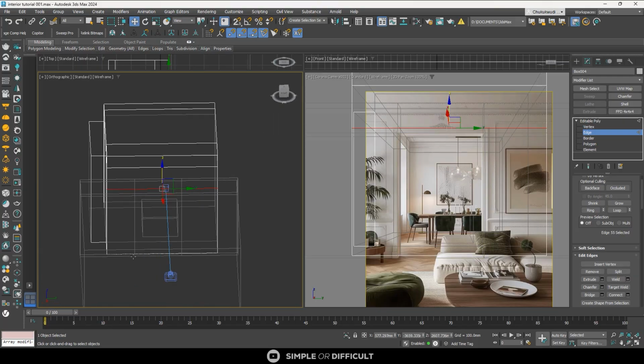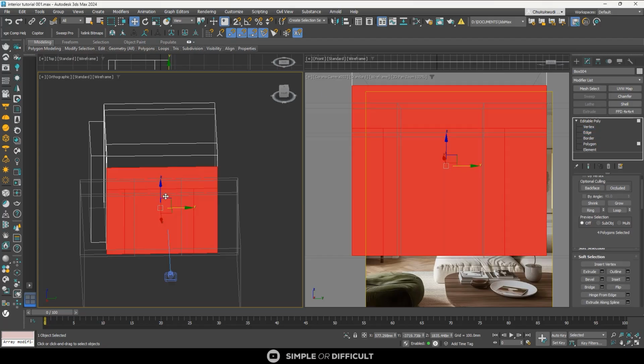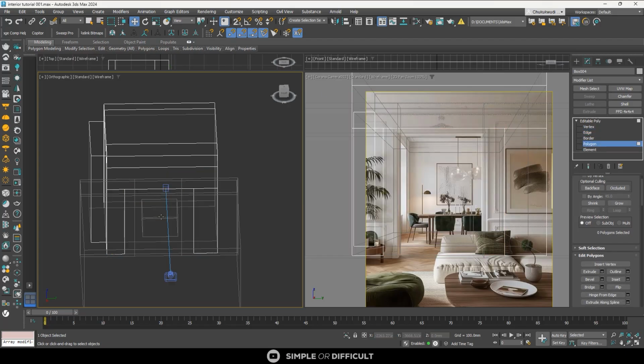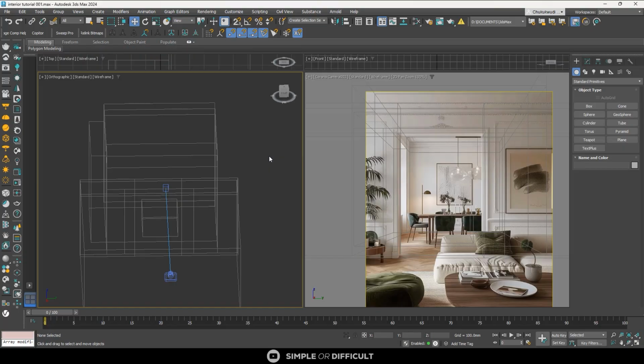And then with this thing selected, I will select this one, click on the settings right beside the connect, come over here, change this number to 2, and then hit OK. That is going to create 2 lines for me at the same time. Hold down Alt to deselect this so it can go over to this side. Okay, so I'm going to use Key 4 on my keyboard, select this, and then delete it. Right.